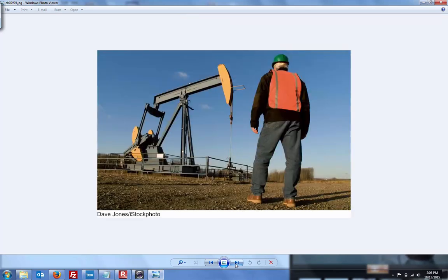And then here, the traditional nodding donkey pump jack. So this is accessing the oil once the initial gusher has dried up. This to me, since we covered Watt's steam engine not too long ago, is very reminiscent of it. This guy on the back side here is more or less your flywheel or your energy storage. And you can see that this nice curve on the front is very similar to those curves we saw in Watt's steam engine, where you can take this rotational motion of the pump and turn it into this reciprocating motion to bring the oil up.